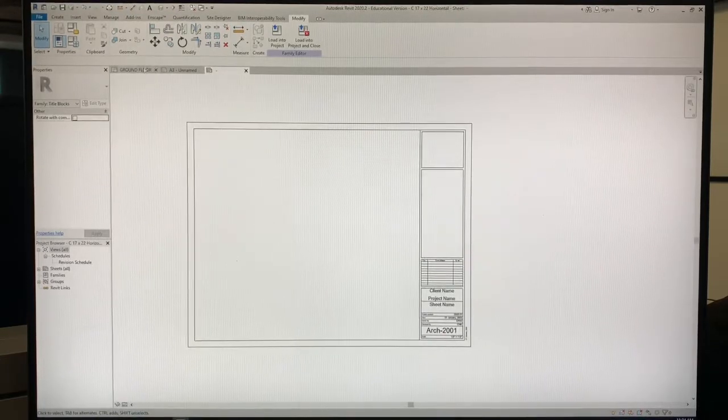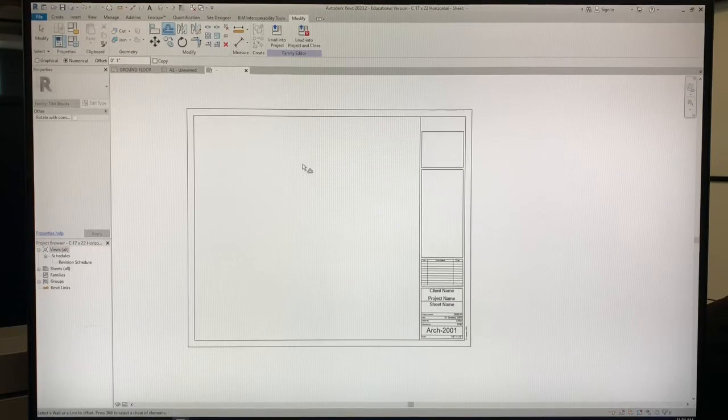So, here we go. Go to your Modify tab. In your Modify panel, please use the Offset tool. We're going to offset it first 1 inch upwards, so please put 1 inch. And turn off your copy option. I don't want to copy, I just want to move the object 1 inch. The vertical length right now is 17. I want to make it 18. That's why I'm offsetting it 1 inch. So offset the top by 1 inch, and offset the border also by 1 inch.